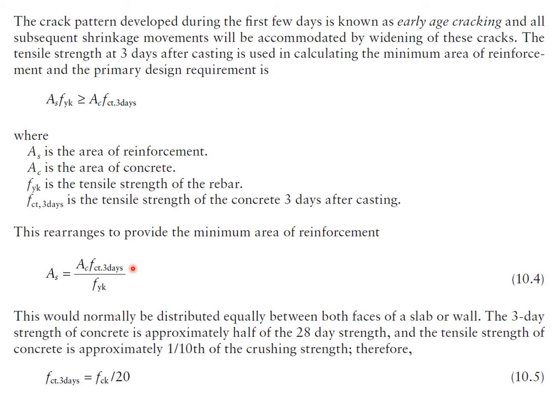The 3-day strength of concrete is approximately equal to 1/2 of the 28-day design strength of the concrete, and the tensile strength of concrete is approximately 1/10 of the crushing strength. Therefore, the 3-day tensile strength is approximately equal to 1/20th of the 28-day design strength.